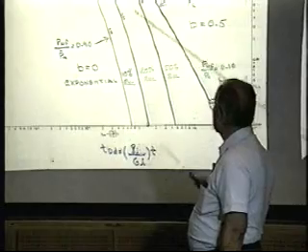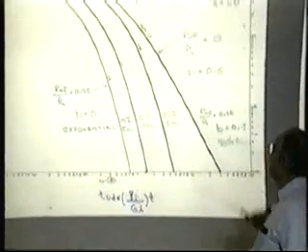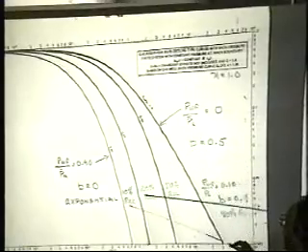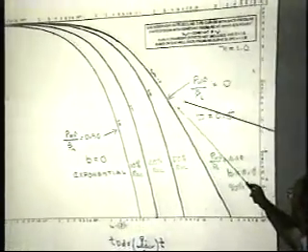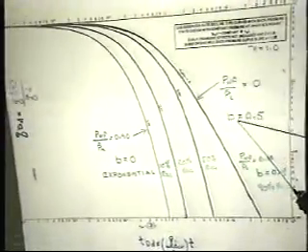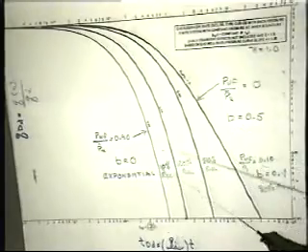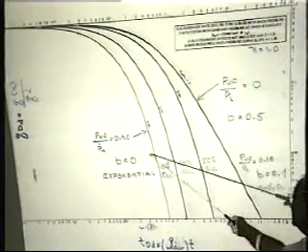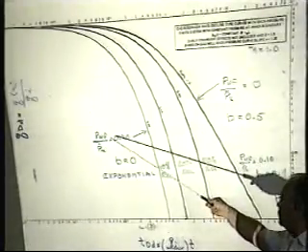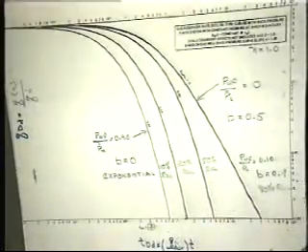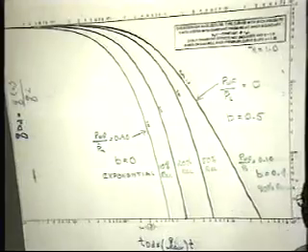I need to introduce here an example with a slope of 1 and different back pressures. Your PWF over P is 0, with a B of 0.5. It's exact from the equations. If you let the flowing pressure approach the shut-in pressure, like this limiting case here, where the flowing pressure to shut-in pressure ratio is 0.9, it's exponential. So the value of B is also a function of the back pressure.